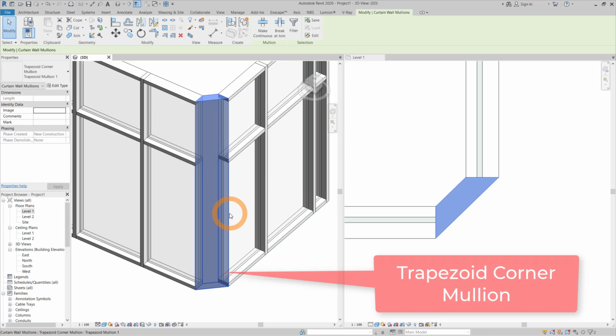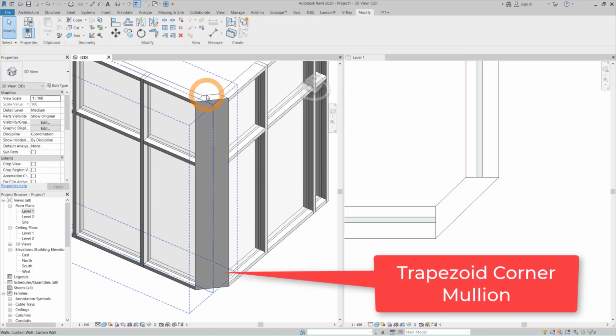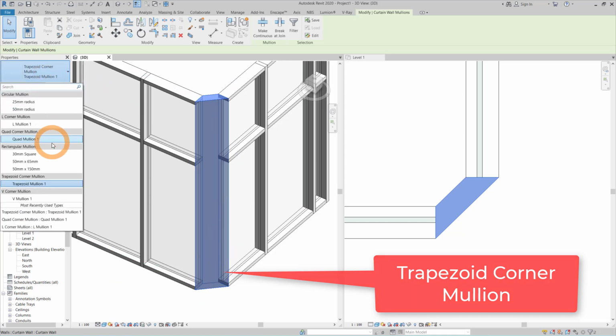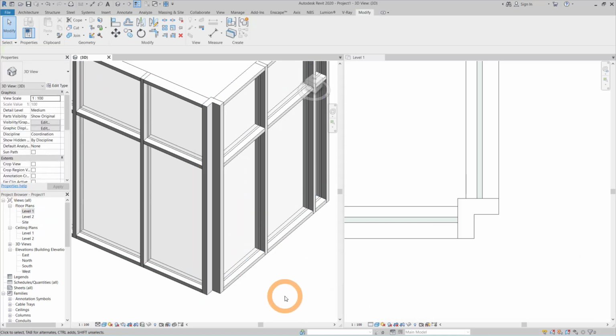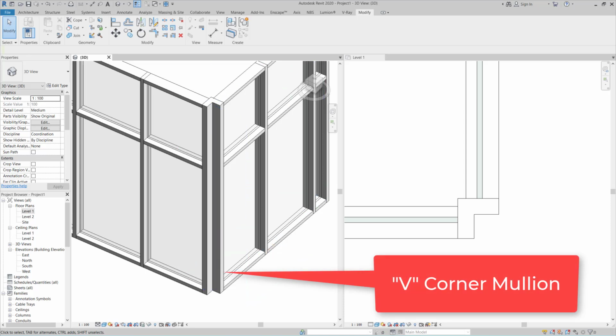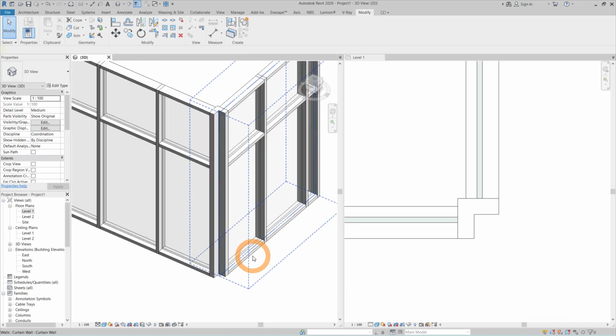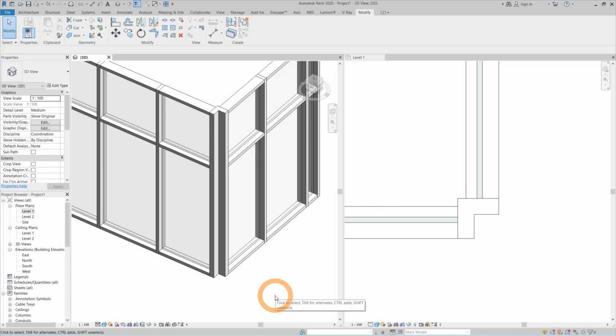So what we have looked at so far in this tutorial is how to create a curtain wall from scratch. In reality there will be many instances where you don't want to go through this process each time. This is when we would look to a curtain system. This is where we predefine the composition of our curtain wall in terms of panel type, spacing of the horizontal and vertical grids, panel offsets, etc. We can set that up once in our office template, and have it available for each new Revit project we start.